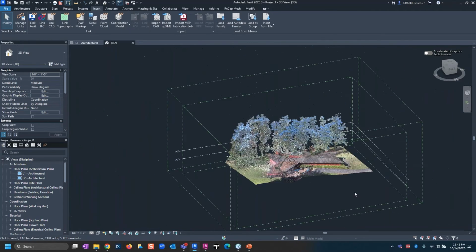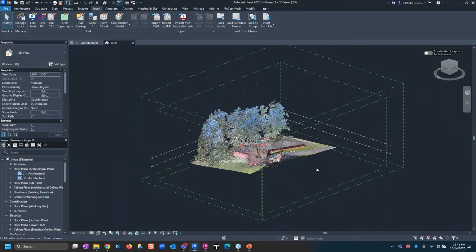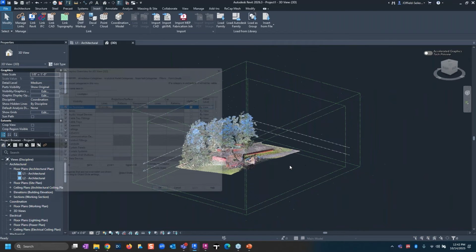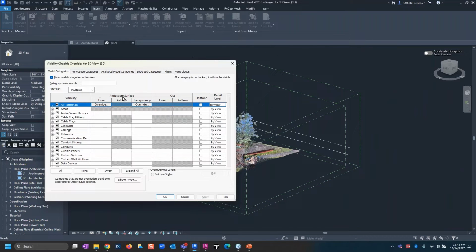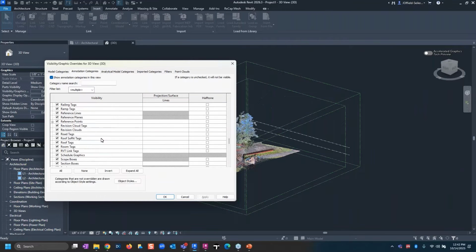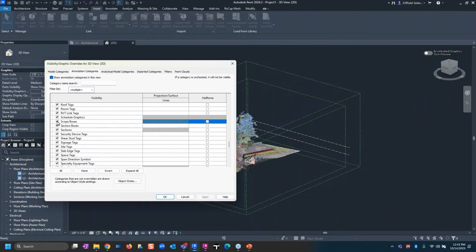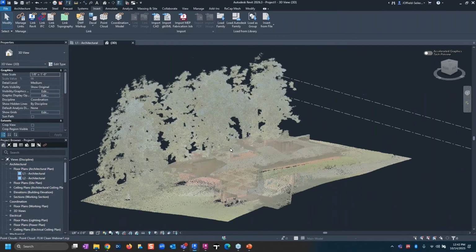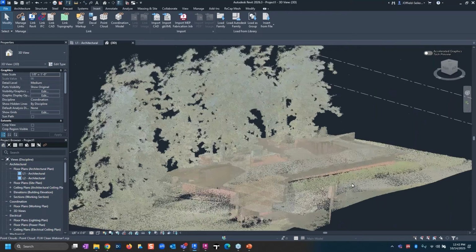And these boxes that you see, these were just some of the default scope boxes. I'm just going to go get rid of those here, and we'll get those shut down. And so there's those scope boxes. We'll turn that off so we don't have anything else wrong there.